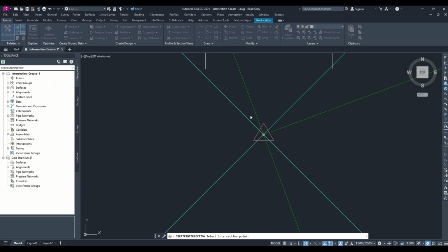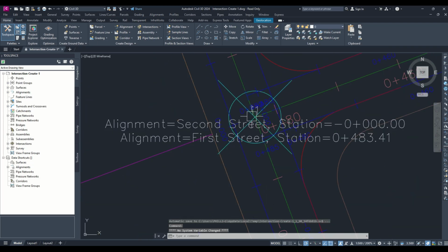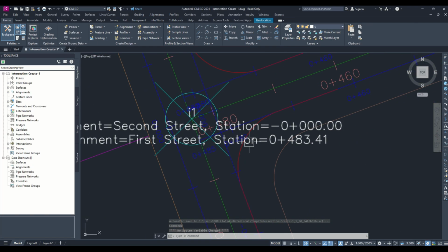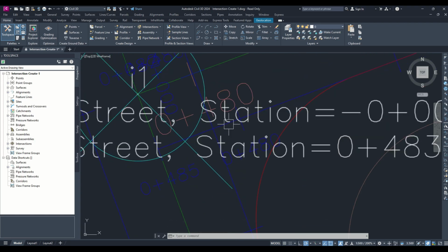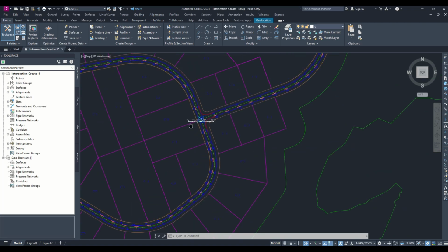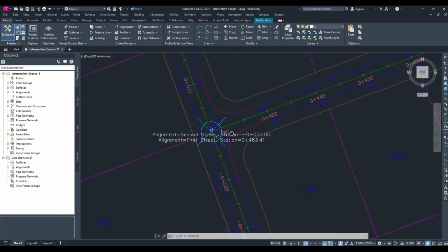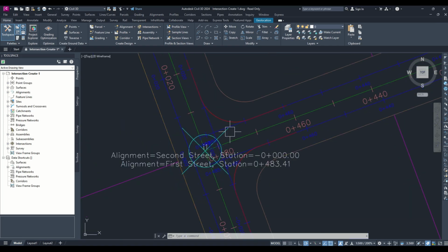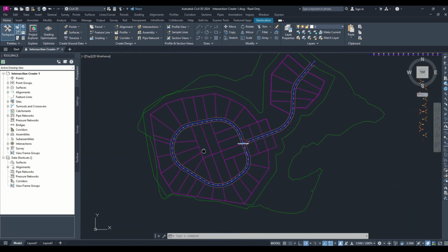So it's just going to create these alignments here. As you can see, this is an alignment for the cable chain. It's not a 90-degree bend as it shows here, so I have to follow this cable chain. For most of you, I know when you do your corridor, it intersects here with a 90-degree bend. So I'm going to help you deal with that.